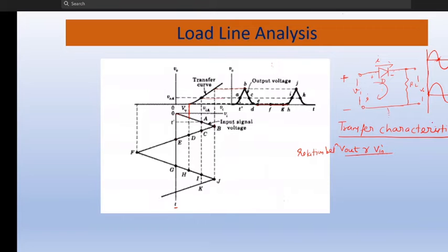It is happening because of the capacitances. When you go to very high frequencies, you can try it in Multisim. What happens? Xc equal to 1 upon 2 pi f c. So once you go to a very high frequency, this reactance becomes 0, and once this reactance becomes 0, the current starts flowing.